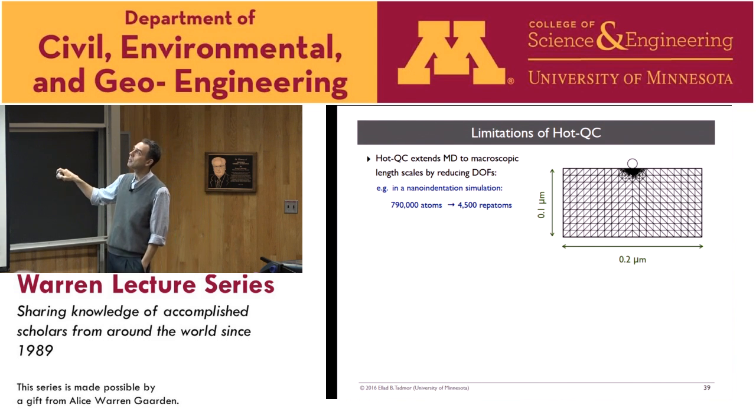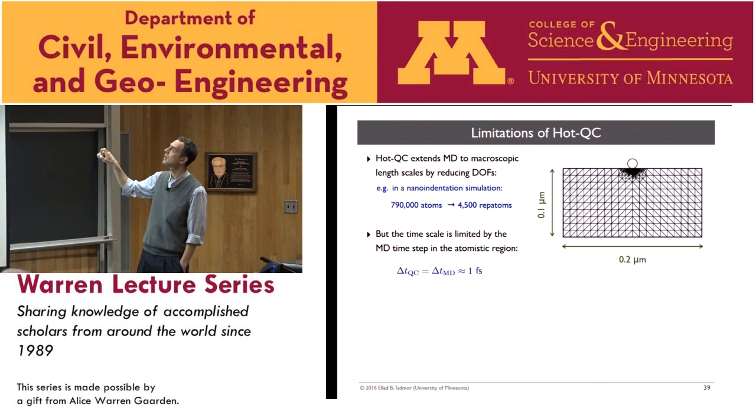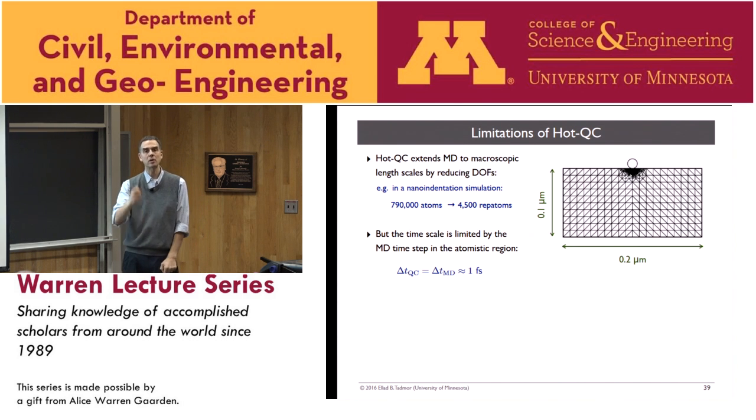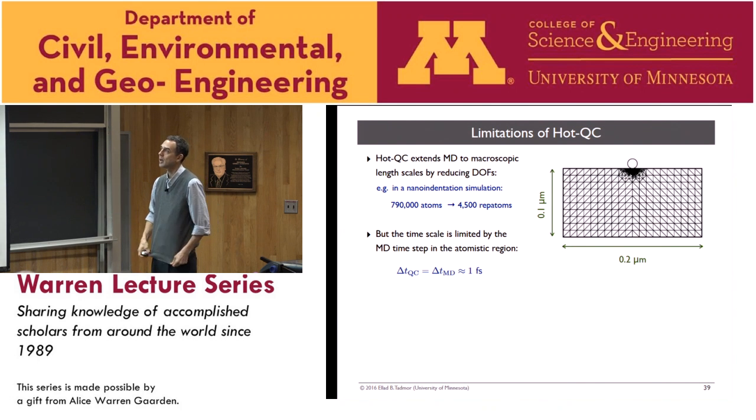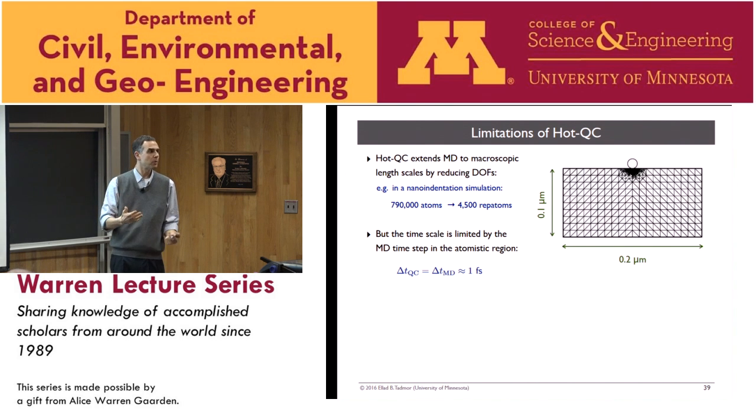But there's still a problem with this. Yes, we can go to much larger regions. We can approach micron scales. We can go much bigger than this now. But we're still stuck with this time step, because the MD integrator clicks every femtosecond. And that means we're stuck with not being able to reach long time scales. This is why, if you open the literature and read molecular dynamics simulations, they're almost always done at rates that are much, much higher than reality for the problem they're studying.